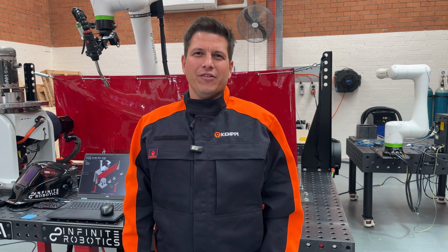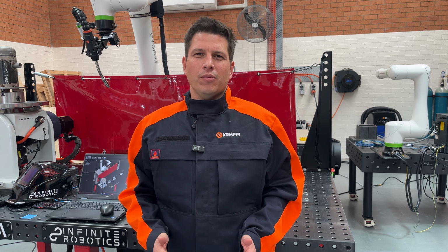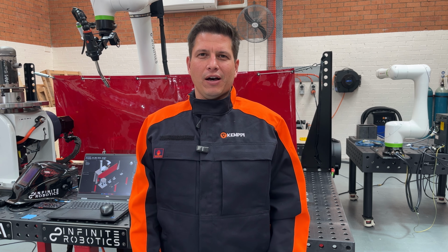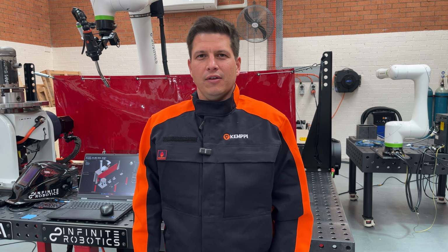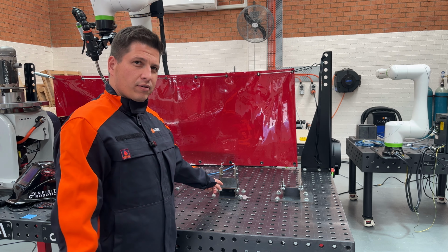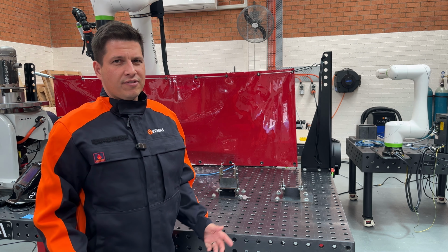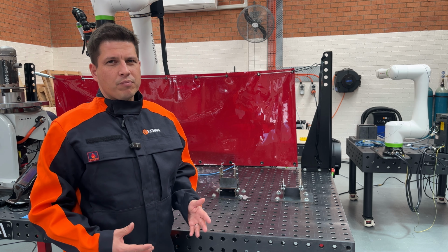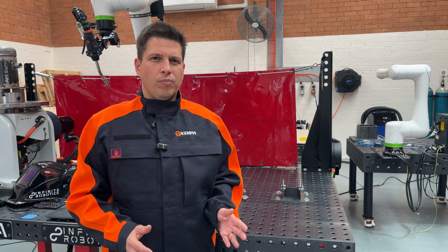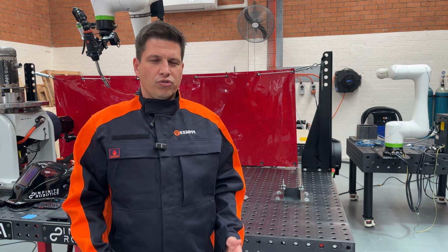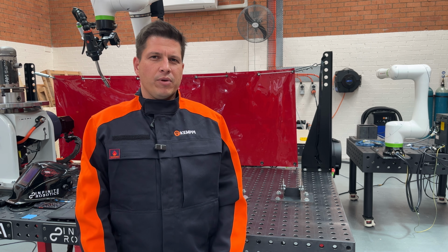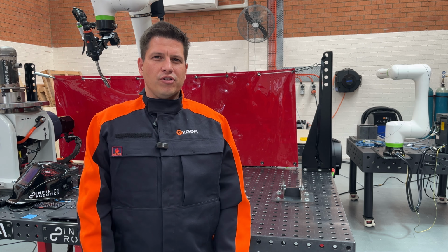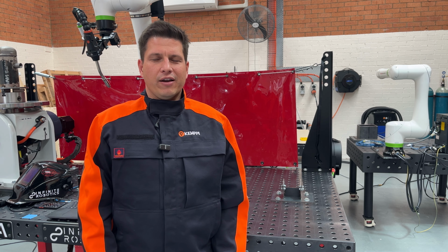In today's video, we're going to run through another method of programming your welding robot, and this method will use your CAD models to automatically create the path for your robot, including touch sensing. So in today's demo, we're going to weld along this test piece here, just a simple fillet weld to demonstrate the concept to you. But generally, it'll be the same process to follow whether you're welding a small part or a big part, and we'll show you how much time you can save programming offline, and you can compare it to how long it would take you to program using traditional manual guided teaching or via a teach pendant.